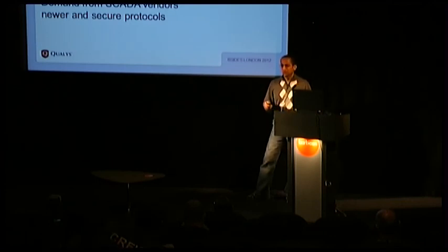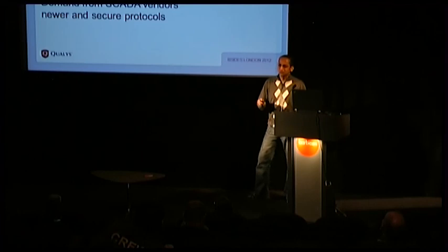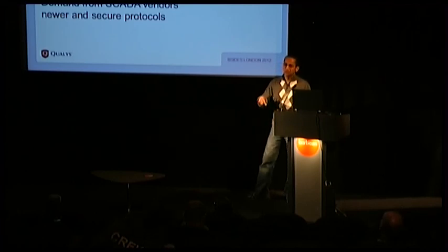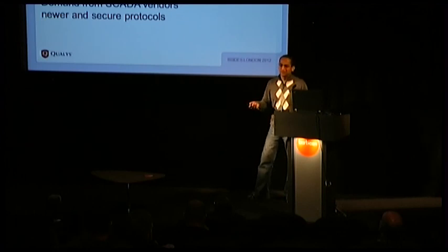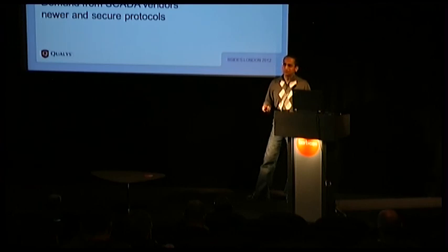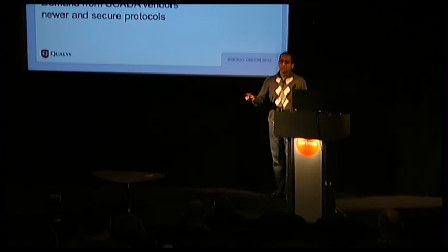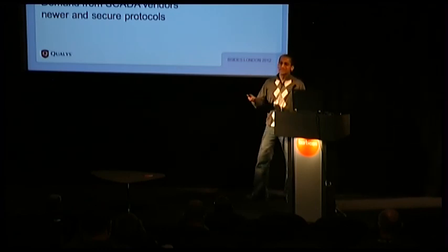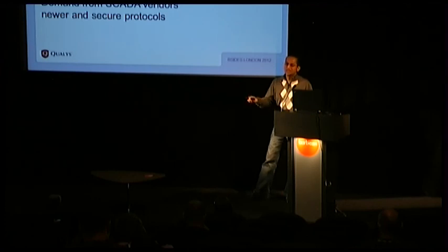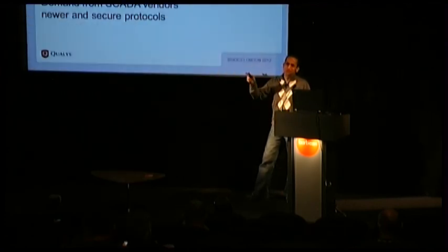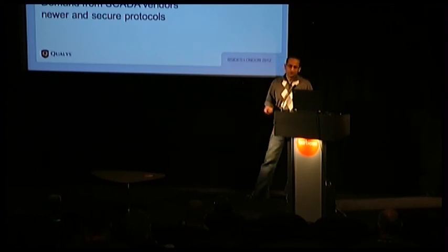Demand secure protocols, and not just from your vendors, but make sure that you are running secure protocols, because we have seen way too many times in SCADA or even in our regular IT network that your systems have the latest and greatest secure protocols, but they are not enabled. So even though you have secure DNP3, the communication is still happening just in DNP3. It's not just a checkbox on paper saying I have a secure protocol, it has to be running.